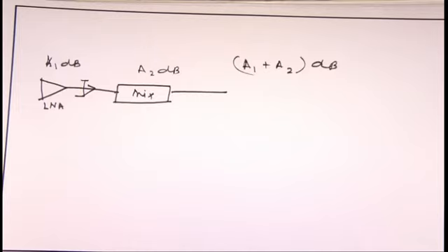So, remember that when you are working on the LNA, try to design a mixer just for the sake of your measurement clarity and easiness. It will be much easier to characterize an LNA if you have a mixer down converter. Otherwise, you have a mixer outside and you down convert it like that.